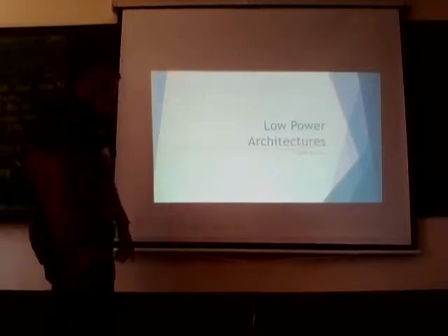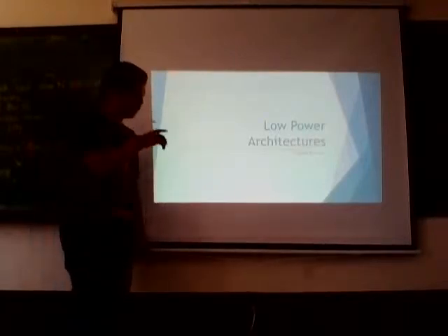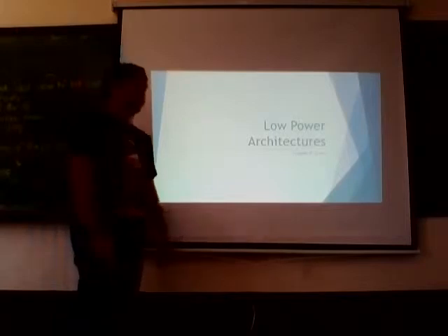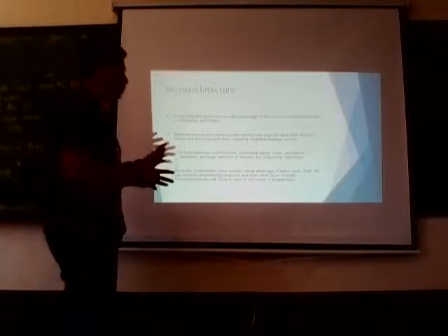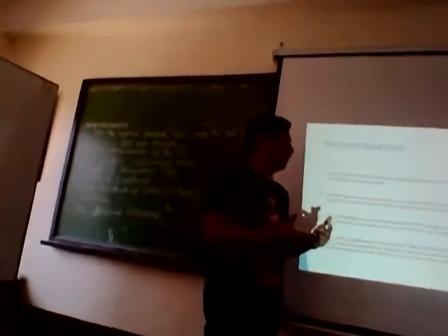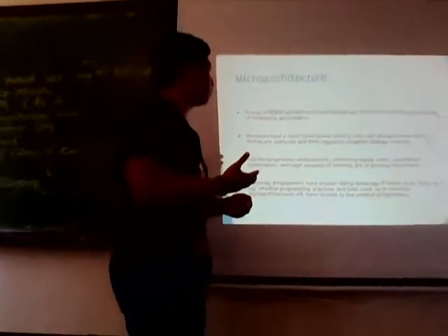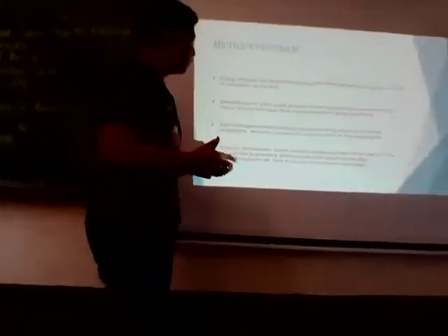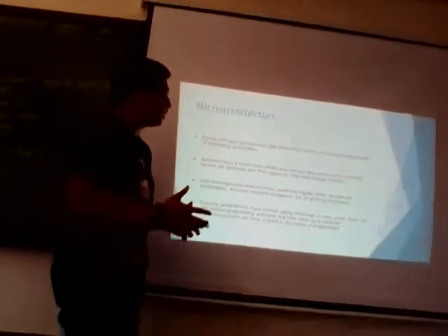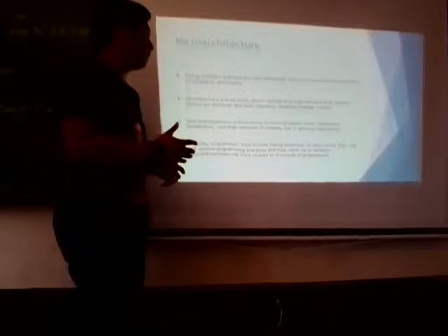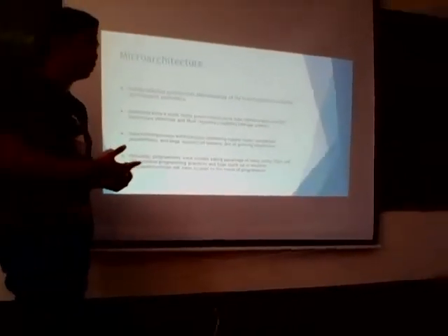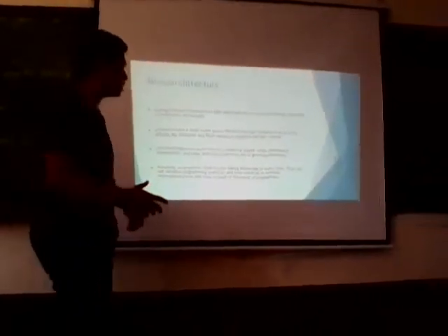Next. So we go to 5.5, low power architectures. Next. First is the microarchitecture. Energy efficient architectures take advantage of structured design principles of modularity and locality. Memories have a much lower power density than logic because their activity factors are minuscule and their regularity simplifies leakage control. Such heterogeneous architectures, combining regular cores, specialized accelerators, and large amounts of memory, are growing in importance.